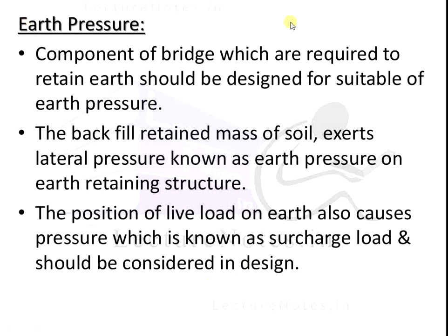Next, earth pressure. Components of the bridge which are required to retain earth should be designed for suitable earth pressure. The backfill retained mass of soil exerts a lateral pressure, known as earth pressure, on the earth retaining structure. The position of live load on the earth also causes pressure, which is known as the surcharge load, and it should be considered in design.